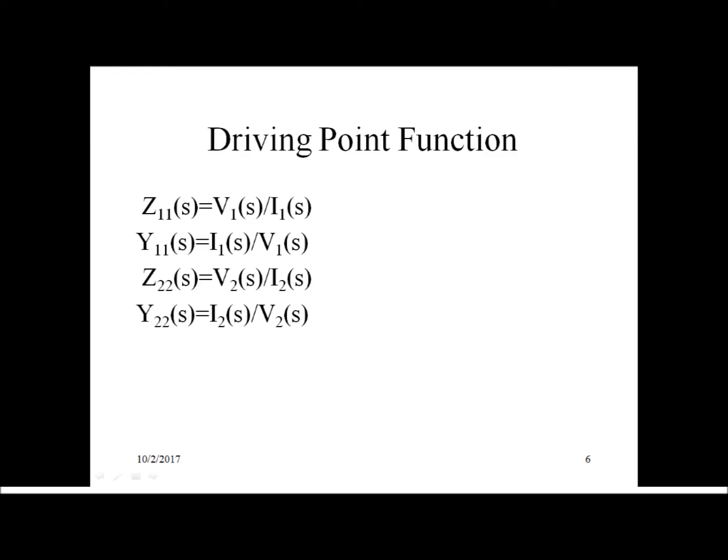Driving point functions: Z11 is V1 upon I1, Y11 is I1 upon V1, Z22 is V2 upon I2, Y22 is I2 upon V2, everything in the frequency domain, so in the s domain.